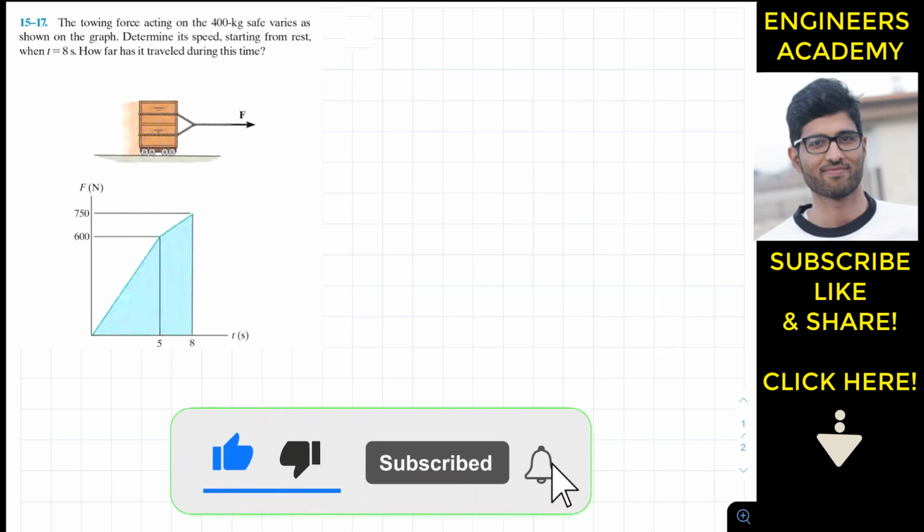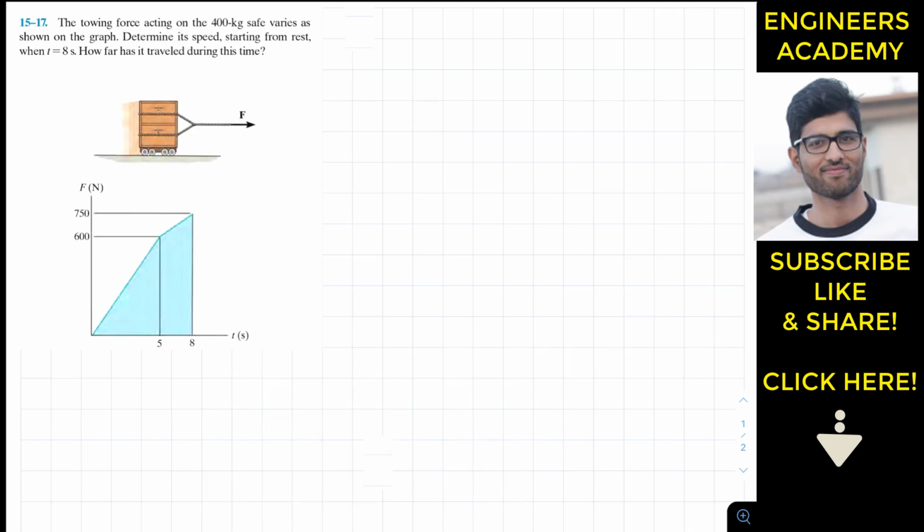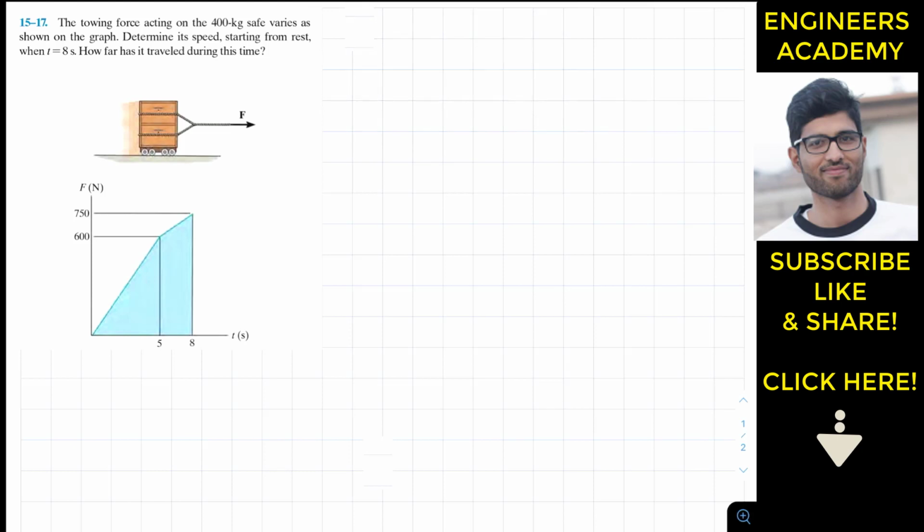Now we are going to solve another problem from chapter 15, Hibbeler Dynamics. The problem says that the towing force acting on the 400 kg safe varies as shown on the graph. Determine its speed starting from rest when t equals 8 seconds. How far has it traveled during this time? So we have to find the velocity when t equals 8 seconds, and the distance traveled after t equals 8 seconds.